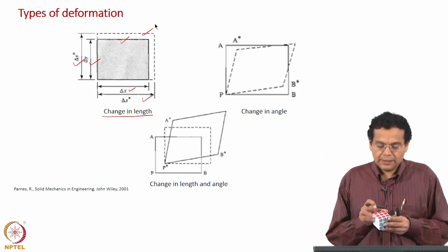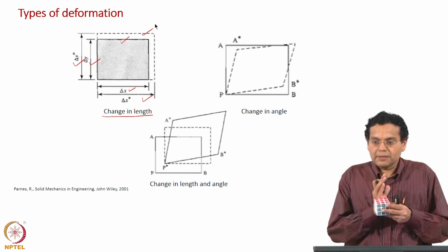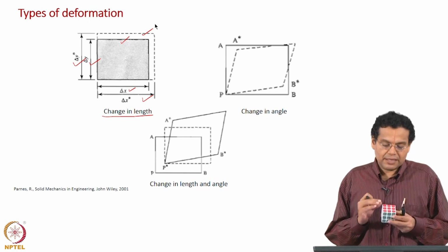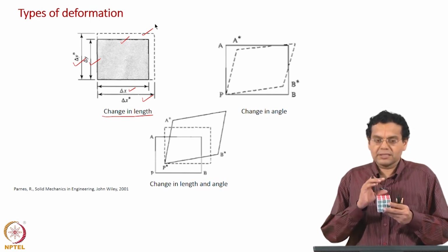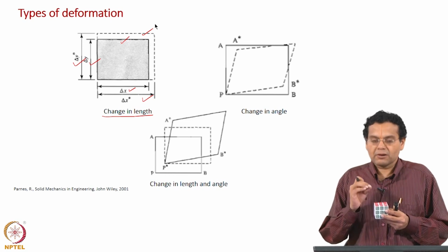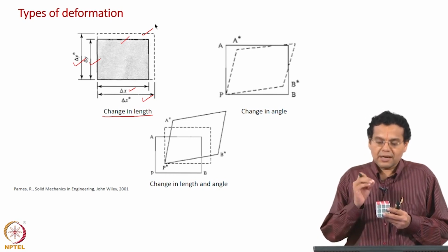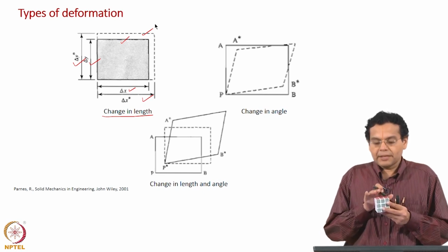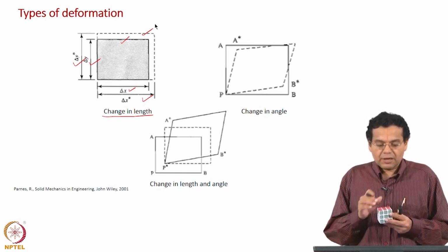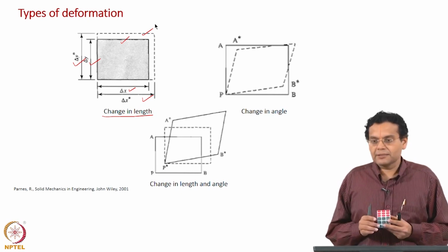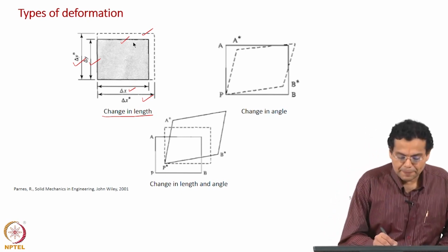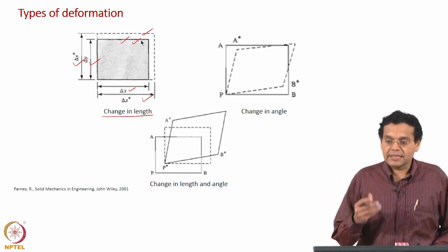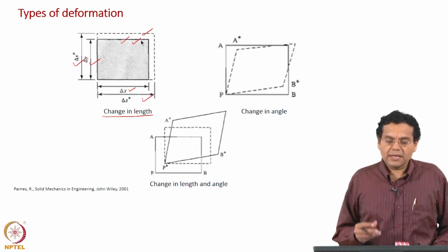In the case of solid, it goes from one equilibrium state to another equilibrium state. I have a solid, and different names are given for the solid or state before applying the force. We can call it the initial state or undeformed configuration. And you apply a force, it undergoes deformation. What does the deformation mean? For example, right now, change in length. So, this continuous line represents the plate in the initial state or in the undeformed state.